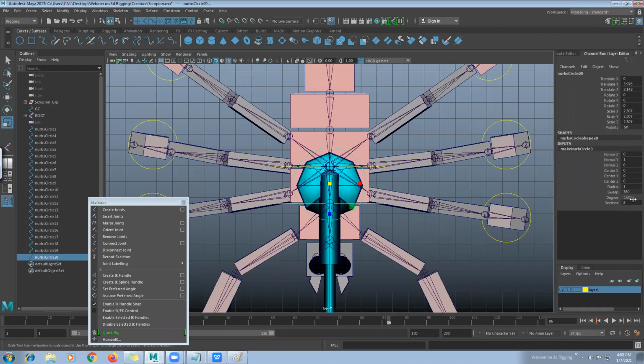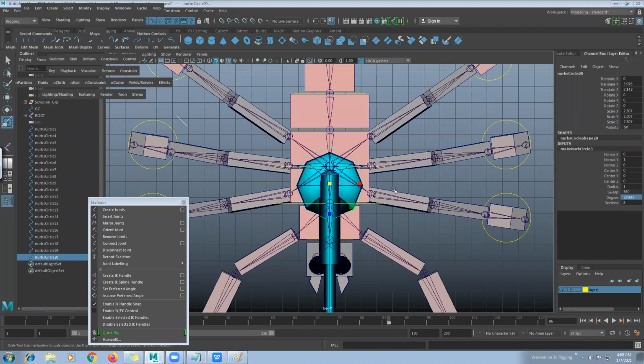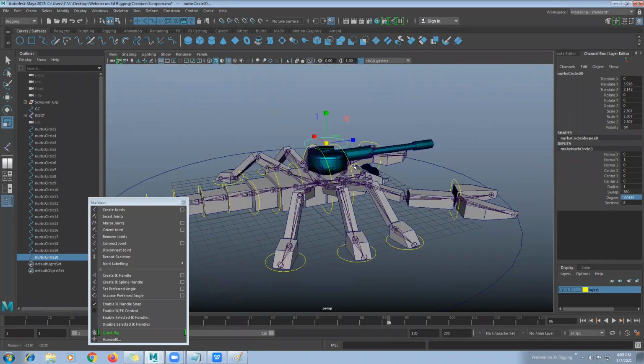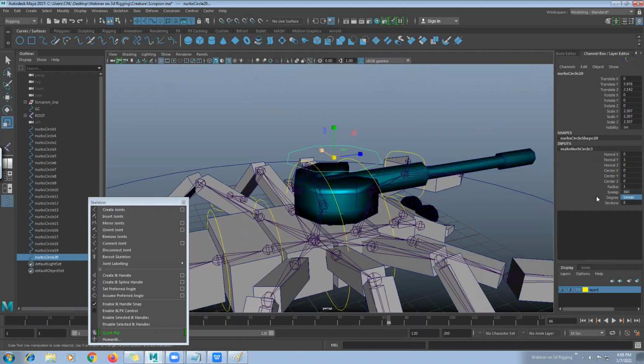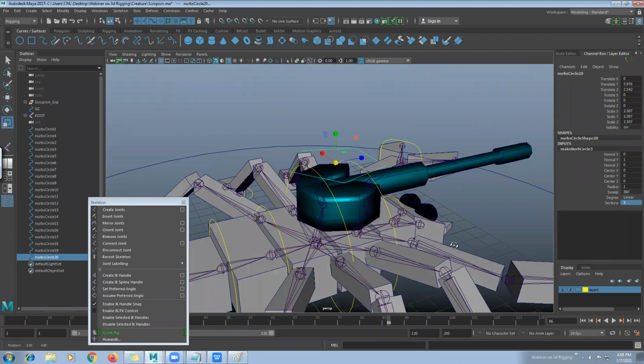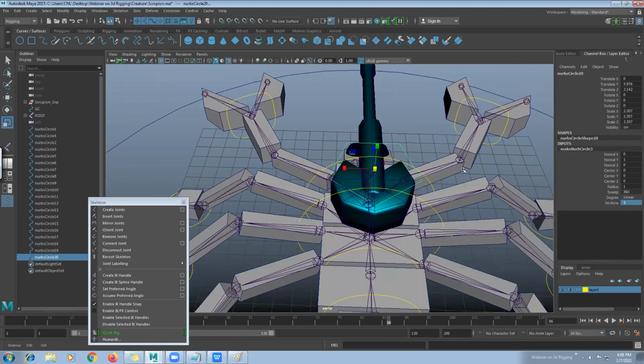You can change this to linear, so it gives you that aesthetic, something like a hexagon or polygonal look. This section is 8, that means it's octagonal. If you want pentagonal, you hit 5 and hit enter. And as per your requirement, you may change this rotation value.